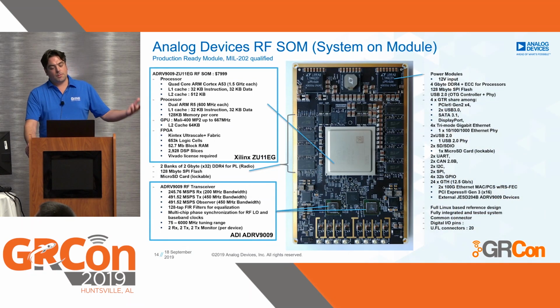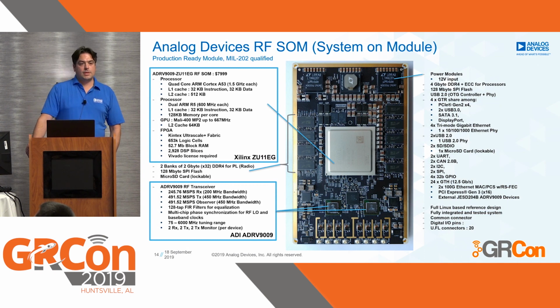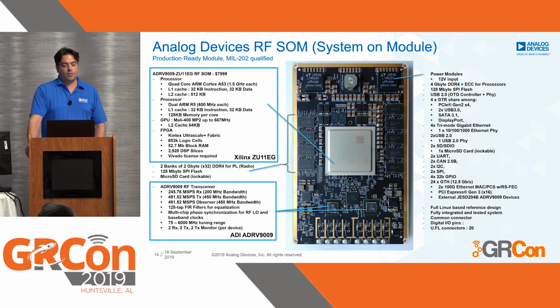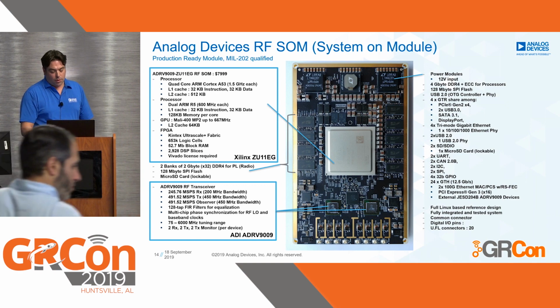The multi-channel system that I'm talking about today is built on the RF SOM. It's basically 2 of those chips, making it a 4x4 on a PCB together with the ginormous MPSoC FPGA from Xilinx. There's, in addition, multiple banks of DDR4 memory and also complete integrated power.